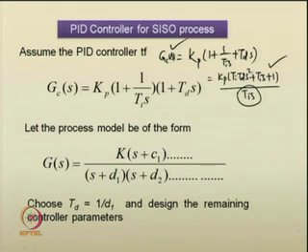So, when we have two zeros given by the controller and the plant is an all pole system, the closed loop transfer function will have two zeros in the numerator. That means the standard transfer functions will have two zeros, for which it is very difficult to find the coefficients d1, d2 and so on.